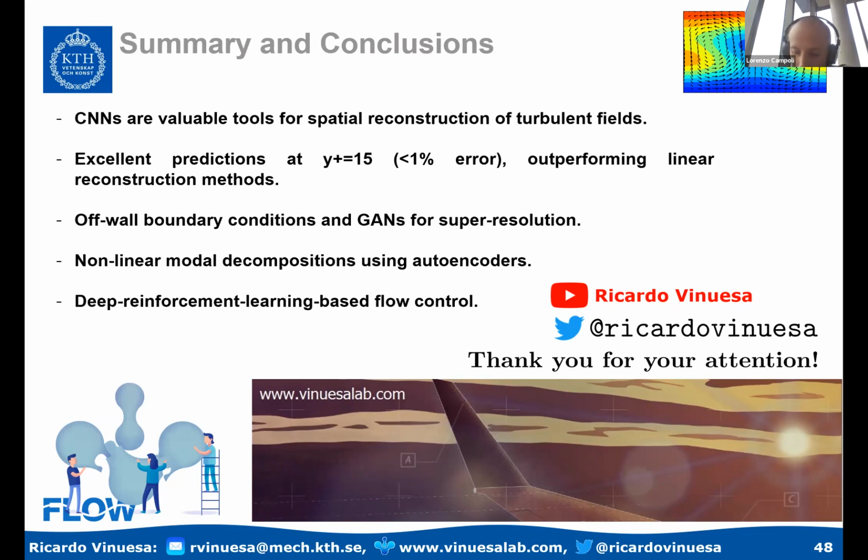The volume was a bit low, but I think I understood the question. We have three fields at the wall as an input, the wall shear stress components and the wall pressure, and all the results that I showed today are based on the three fields. But we played a little bit removing certain fields. We used some explainability of deep learning as well. And we also considered, in an experiment, that the easiest thing to measure is the pressure.